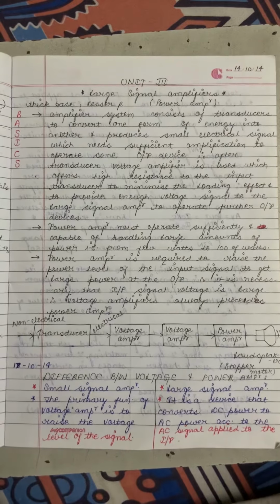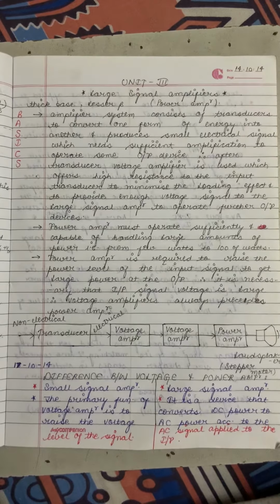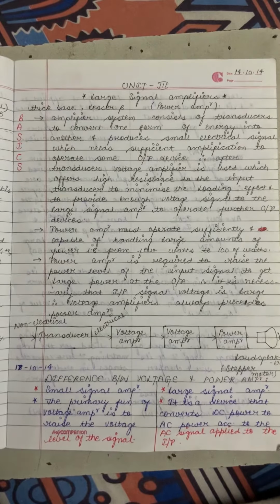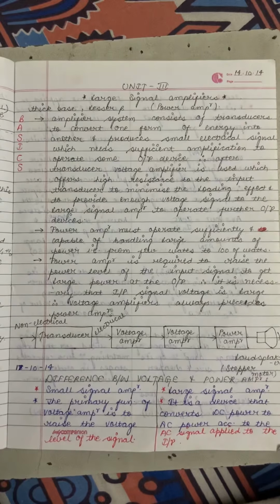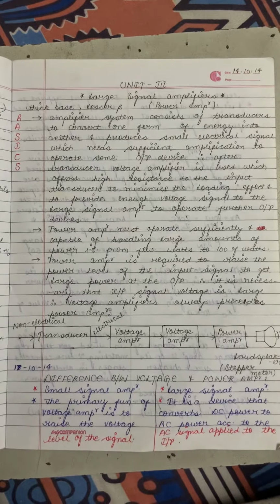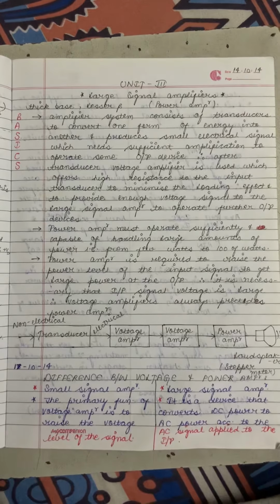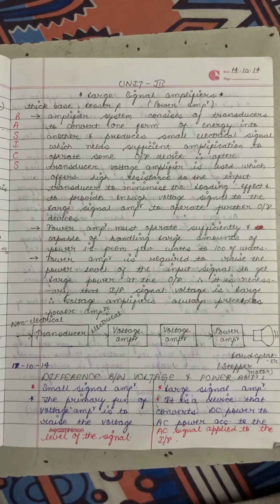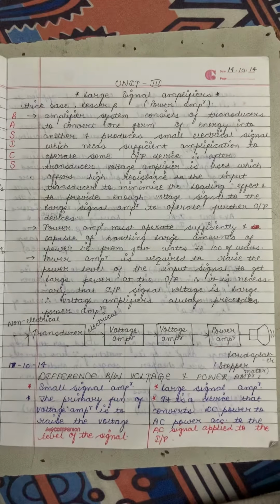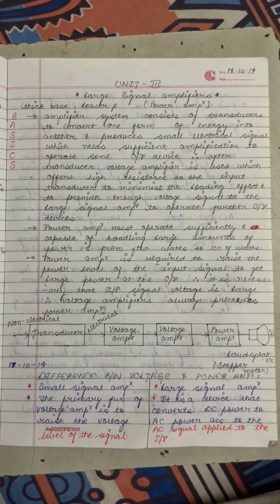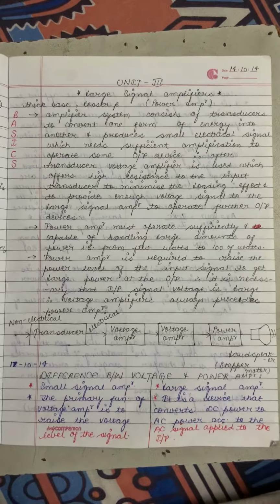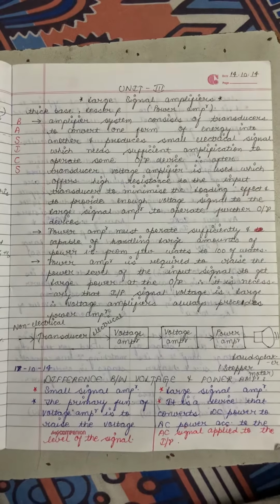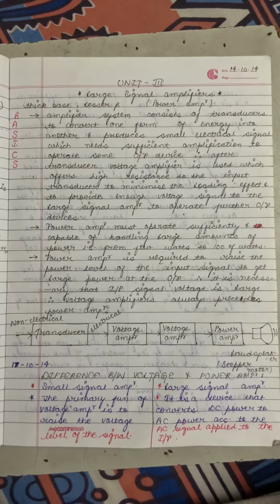This is the basic block diagram showing the different stages of an amplifier. Initially, we have the transducer, and the input of the transducer is in non-electrical form and the output of the transducer is in electrical form. Next we have the voltage amplifier stages, and next we have the power amplifier. And at the output we have the loudspeaker as the output load. We can also use a stepper motor in this case, right? It is a basic introduction of the power amplifier.